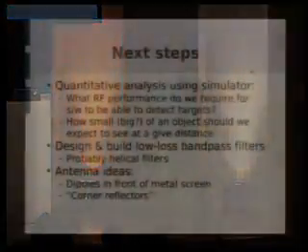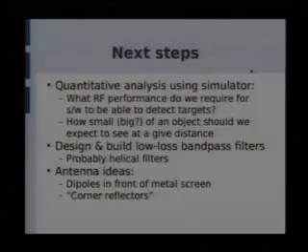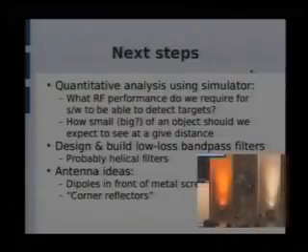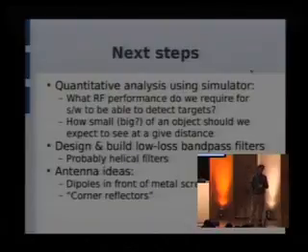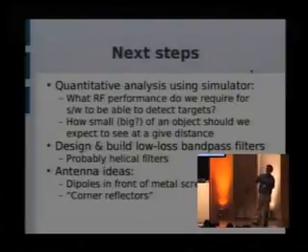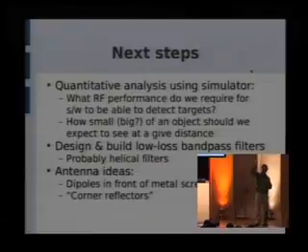So we looked at, and again, this is from looking at some of the literature, what did other people make work? Part of the problem may be that we're getting swamped out by the main path transmitter. You start thinking about this. This reflection off the airplane could be minimum 100 times smaller, 20 dB down from the main path. You've got a spherical wave that's propagating out, and it hits something and then propagates back to you.